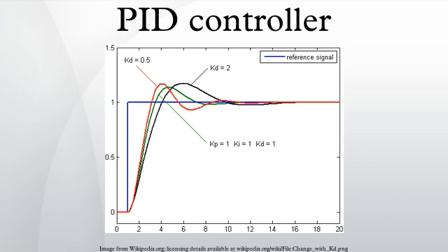The PID loop in this situation uses the feedback information to change the combined output to reduce the remaining difference between the process set point and the feedback value. Working together, the combined open-loop feed-forward controller and closed-loop PID controller can provide a more responsive control system.